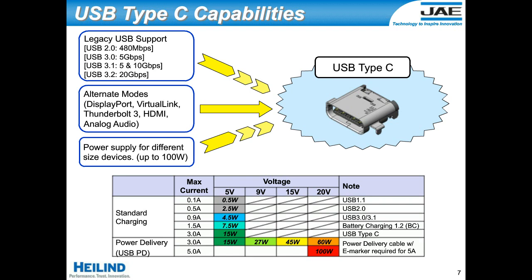So there is some special reassignment of pins that is a little bit different from standard DisplayPort alternate mode. Thunderbolt is also another new standard that's becoming more and more popular for personal computers. Basically, Thunderbolt combines PCI Express signals and DisplayPort video signals into one, muxes those 2 signals and sends it through the standard USB Type-C connector, starting from the